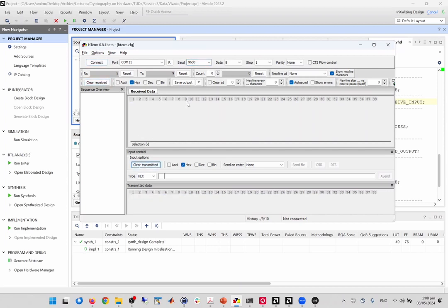You should keep in mind that if you open the H term, by default you have to set the configuration. For example, you need to set the COM port. It might be the case that you don't know which COM port you have, but if you open the H term and get the list, in this case, my laptop doesn't have any other COM port.